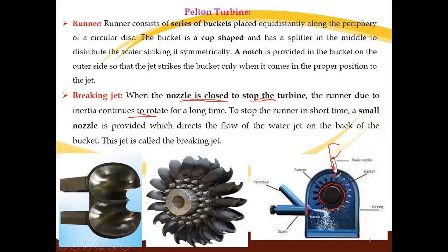Because of that, the runner stops in a short time. That small nozzle jet is known as the braking jet, and that nozzle is called the braking nozzle.